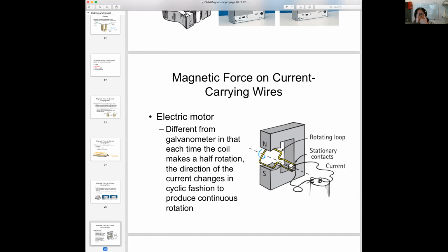So when it turns 90 degrees, parallel to the magnetic field, it disconnects momentarily and then flips the direction of the current, voltage plus-minus to minus-plus. The force that was initially applied up is now applied down, so it changes the direction. Again it goes anti-parallel, disconnects momentarily, inertia carries it, and it goes up and down, up and down.